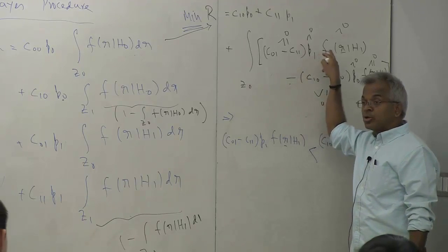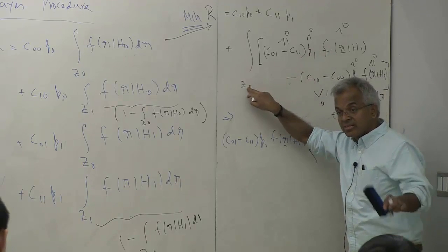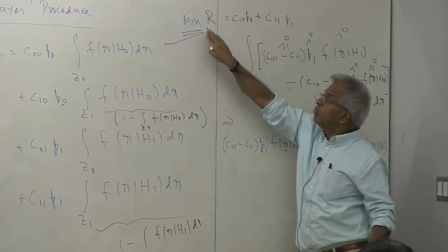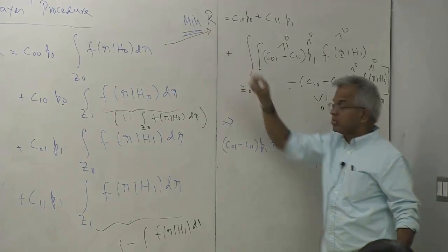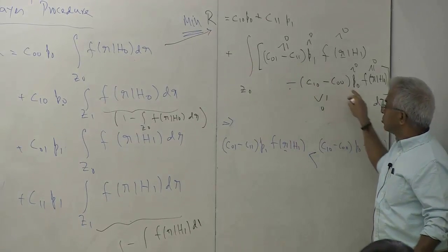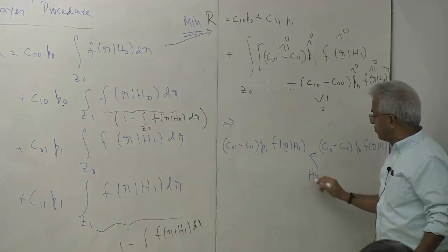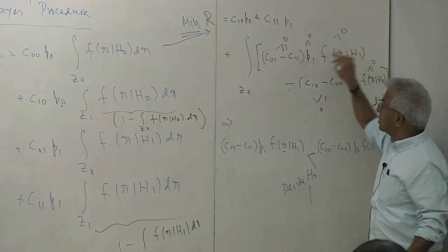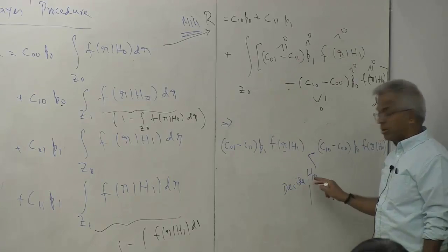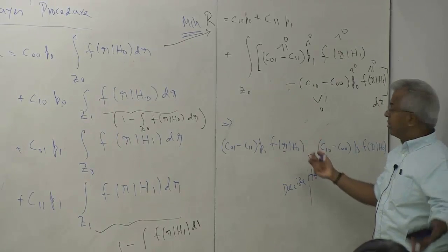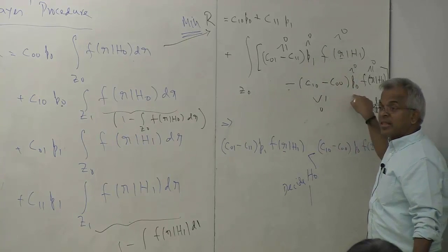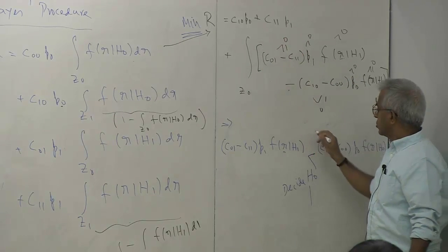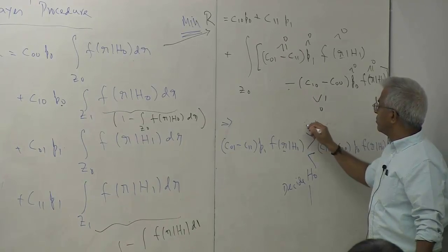And then indeed, you should keep that r in Z0 because that's the right place, because then something is being subtracted from a positive quantity and you are helping to minimize this. So if this quantity is smaller than this, we should decide in favor of Z0. That's what I mean by H0. And conversely, if this quantity is greater than this, don't put it in Z0 because you are only going to increase the risk. So if it is greater, you should decide in favor of H1.